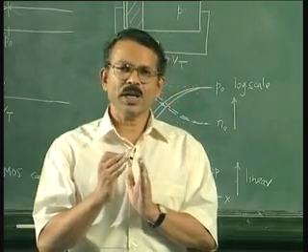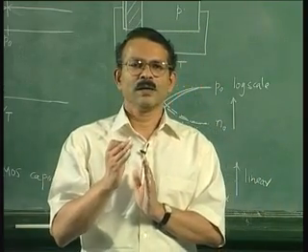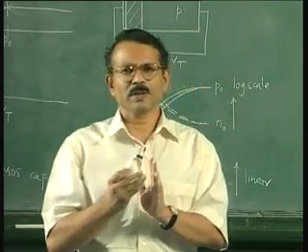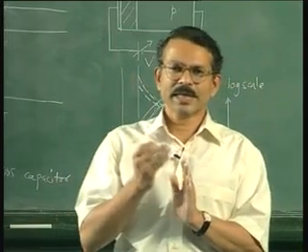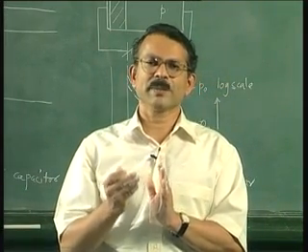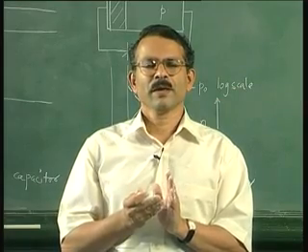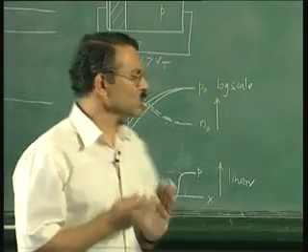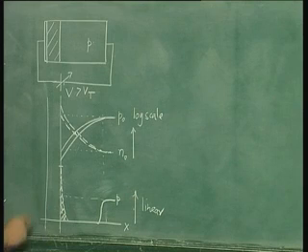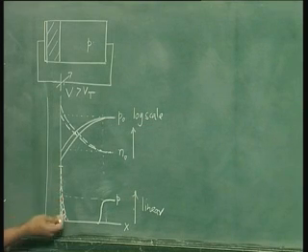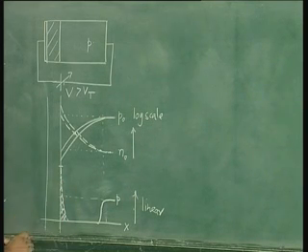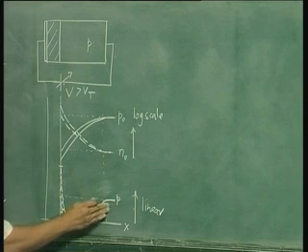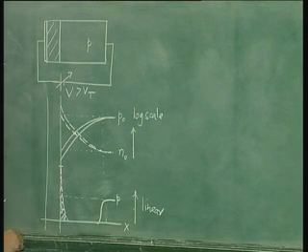But once you go beyond threshold, the extra negative charge comes from the mobile electrons very close to the surface. And since this mobile concentration can now increase very rapidly, there is no need to expand the depletion layer to provide for this negative charge.